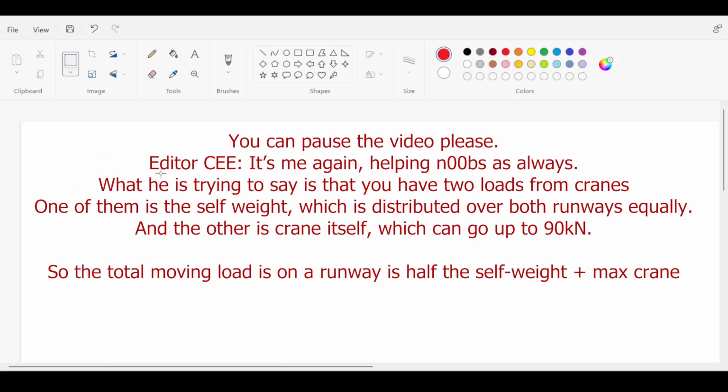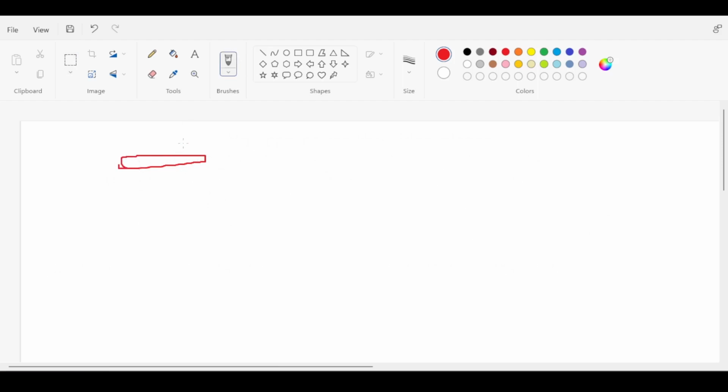Okay, there's something I missed very quickly. I want to repeat the crane thing. If you have a crane girder with a crane on top of it, there is of course the dynamic part which moves, which is the 100 kilonewtons, and there is the static part which is the weight of the girder assembly. Please notice that this moving part will have a variable reaction, and we said that we're going to use 90 kilonewtons because we're not going to be able to put this right on top of the girder, which means 90 kilonewtons moving, but wait.